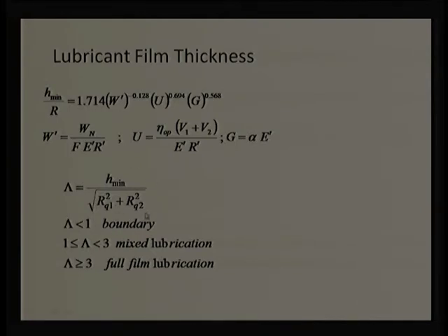If this is 2.3 micron and this is also 2.3 micron, that means we need to keep a film thickness of more than 5 micron between the gears. If the film thickness is more than 5 micron, there is a possibility of lesser positive drive, and in those situations we will again be losing efficiency from the gear. So, we want to operate gears as close as possible, but we also want to avoid wear. It is more like a trade-off. We want efficiency, positive drive, and no wear, and that is why we need some sort of trade-off.